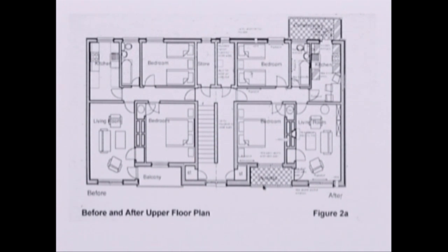To get the buffer space combination down to 0.8 is less demanding. We can then address also upgrading the insulation in the party wall position here and other small parts here with internal insulation. That's the easy bit. The tricky bit is then addressing the heating and ventilation system in an energy efficient manner. And having got the U values down to that kind of level, opaque surfaces 0.1, windows 0.8, really we don't need much of a heating system.